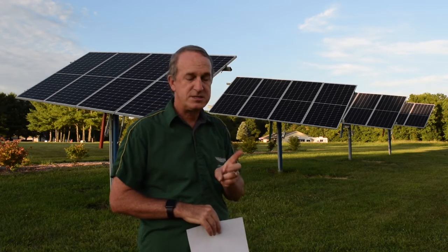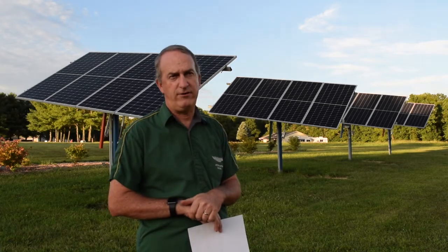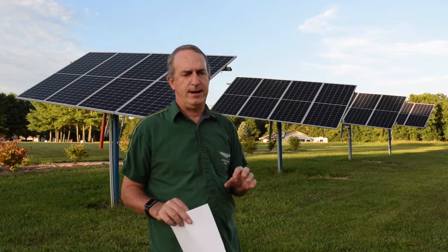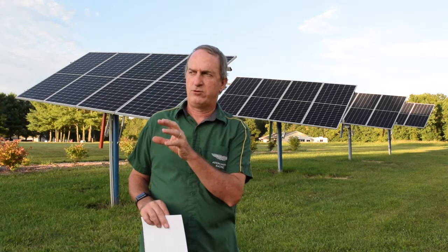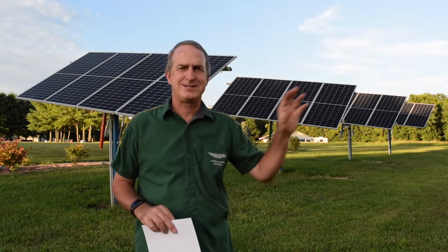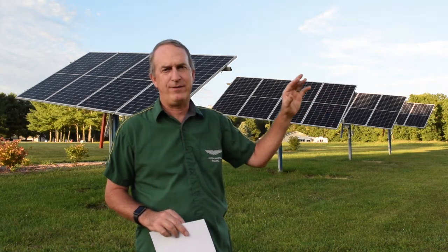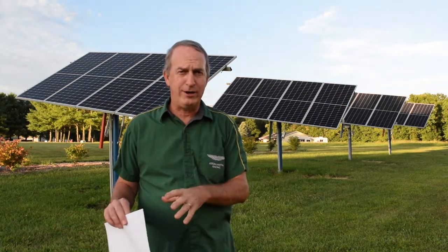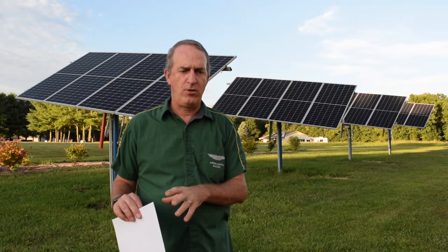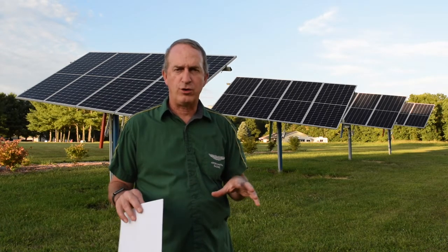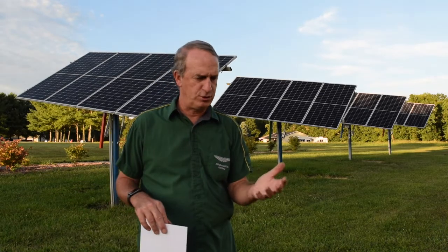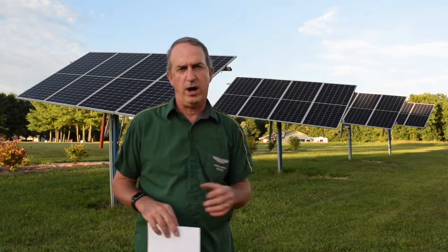That's the first thing. The second thing, which is really clever for a novice installing this stuff, is that the solar panels won't produce voltage unless they're connected to the inverter and the inverter says go. So when you're monkeying around with wires and things aren't all completely set up, the optimizers keep it safe so that there's only 1 volt on that DC wire.